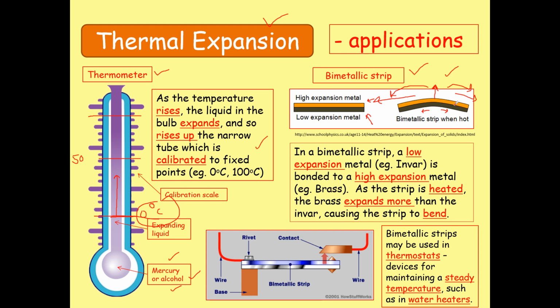And this bimetallic strip, as I said, can be used as a mechanical switch, to operate something, or as an electrical switch, let's say in terms of ironing our clothes, right? We have this setup in our iron. When we are ironing the clothes, we set a specific temperature. That temperature sets the base level of this strip, and once the current goes through this strip, we do know that the iron gets heated up, and when it heats up, it automatically turns off.